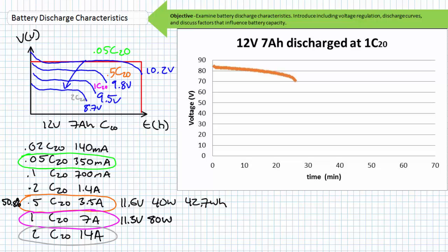Energy is power times time. Every second this battery delivers power, the energy delivered increases. Power is instantaneous in nature, whereas energy is cumulative. When the battery finally reaches the manufacturer recommended cutoff voltage of 9.5 volts over the course of 26 minutes, it has delivered a total amount of only 34.4 watt-hours of energy.